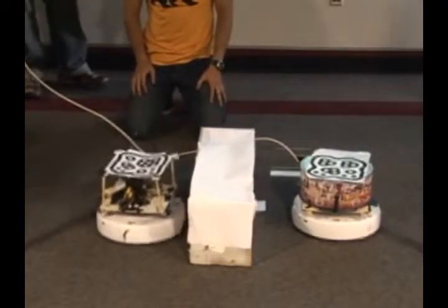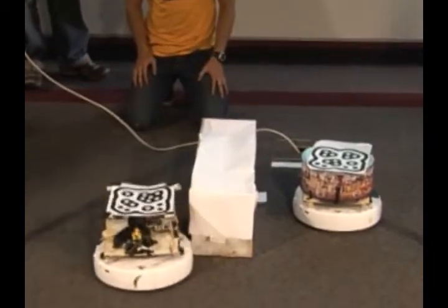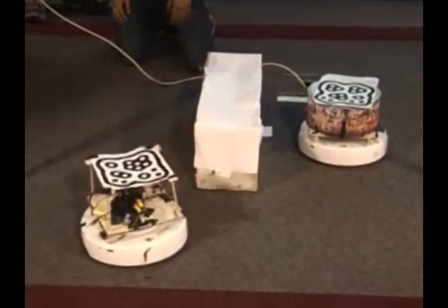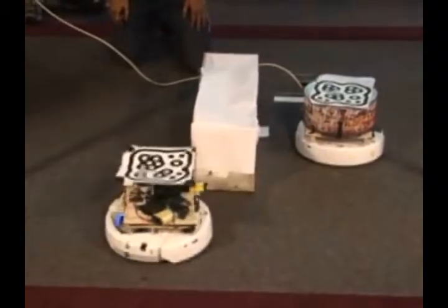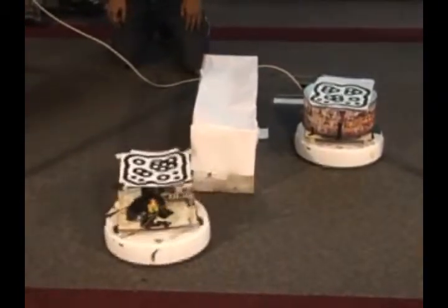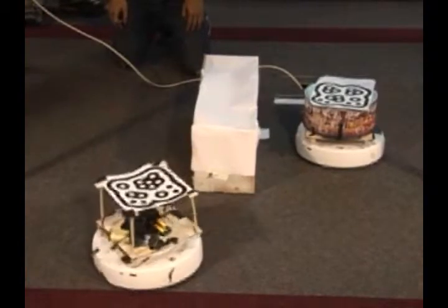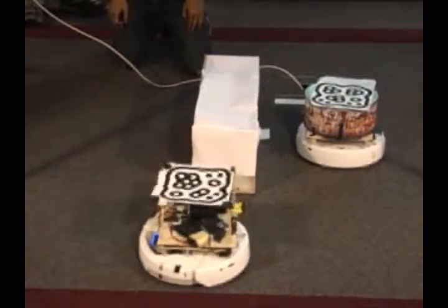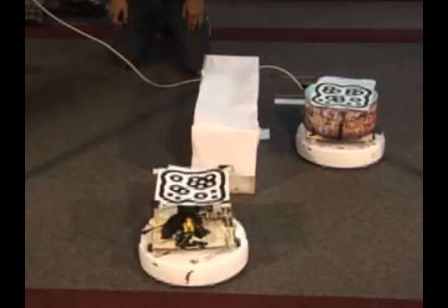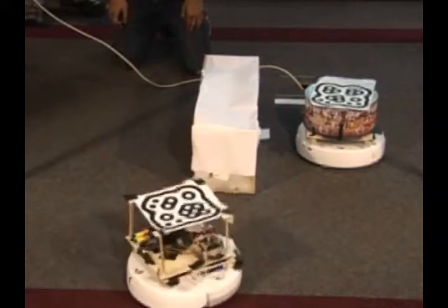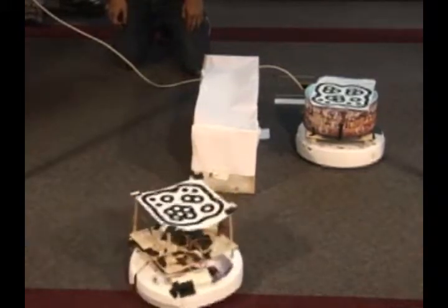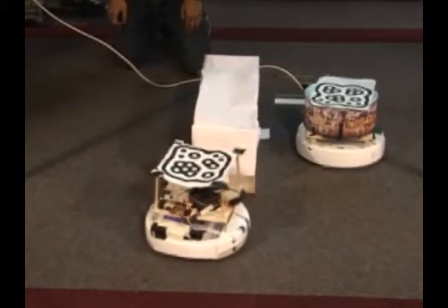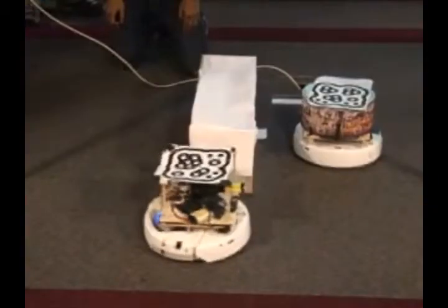So it approached it, and the IR sensor actually hit it, and it's avoiding the obstacle. But it does know where it is, and it knows where the target is. It's doing a breadth first search every single time, and each of those maps is treated as a state, and it's finding it. So it's just determining the best path to go. There's some definition of the best path. Very loose definition of it.